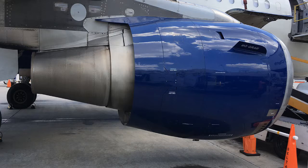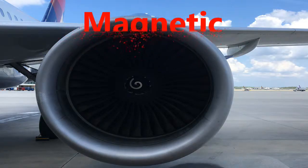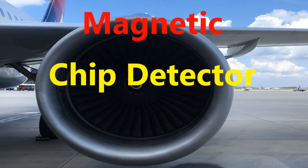And now I want to just touch on the magnetic chip detector. The magnetic chip detectors, there's actually 4 of them, and they consist of a sleeve. You've got the magnetic plug assembly, because you need a magnet there to attract the metal particulates that are in the oil, and then also a spool. You've got a metal mesh screen that's spring-loaded, with a spring-loaded pin to lock the screen in position. You have the magnetic bar there to attract, like I said, those magnetic particles in the oil, so you have that kind of idea there.